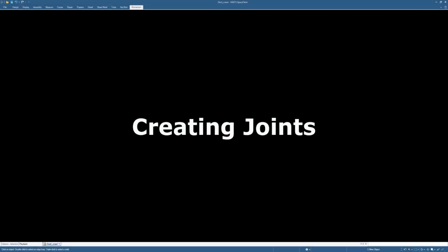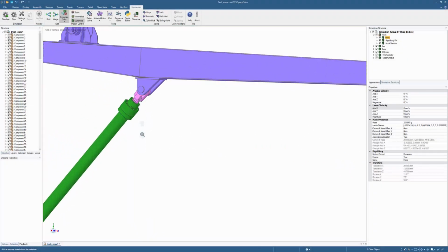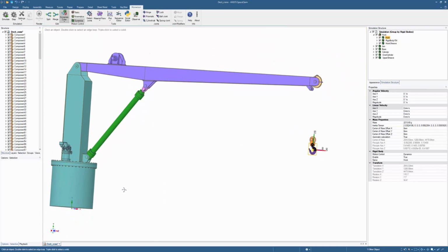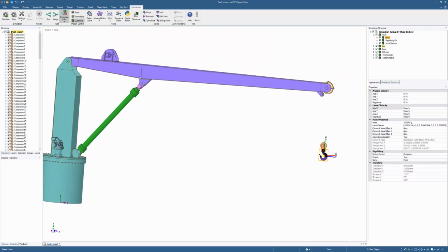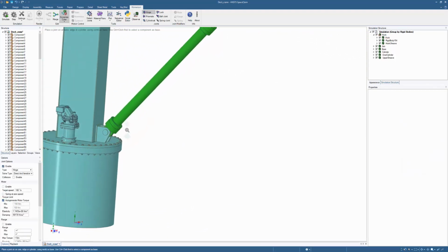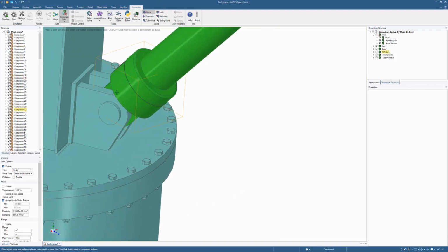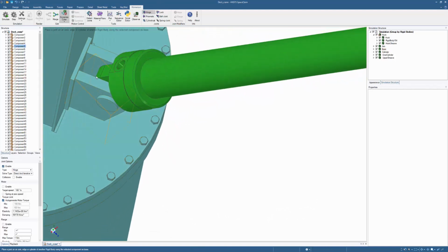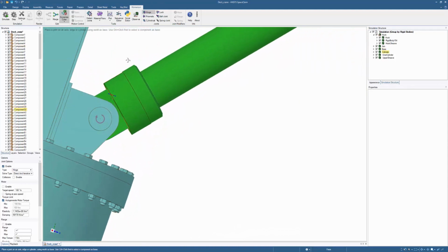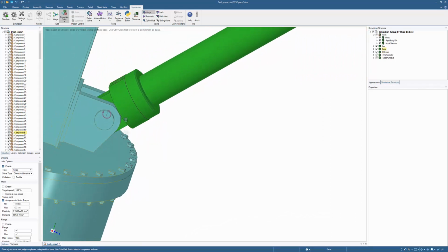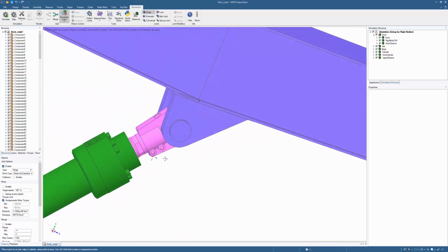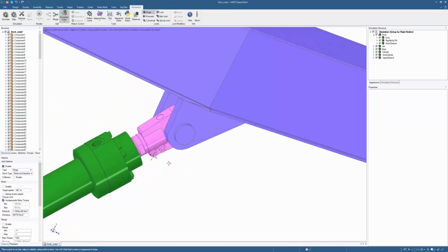Now when we're done separating moving parts into rigid bodies, we can go to the next step, and that's about creating joints. This is a jointed system, and there will be hinge joints, that is rotational joints. So for example, this cylinder here is supposed to have a cylindrical joint around its axis. So we use the hinge tool to create this joint. So we can see that we get a rotation axis around this center line. And there are many ways of creating joints in Algoryx Momentum.